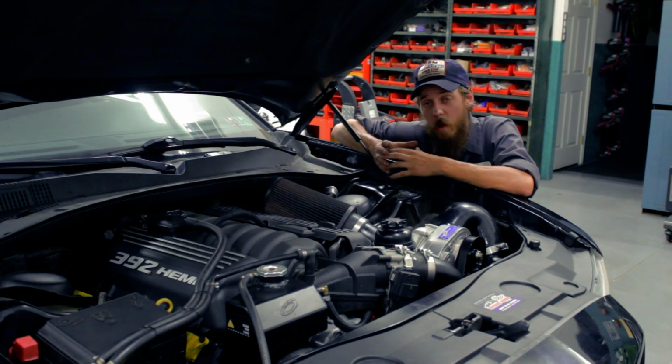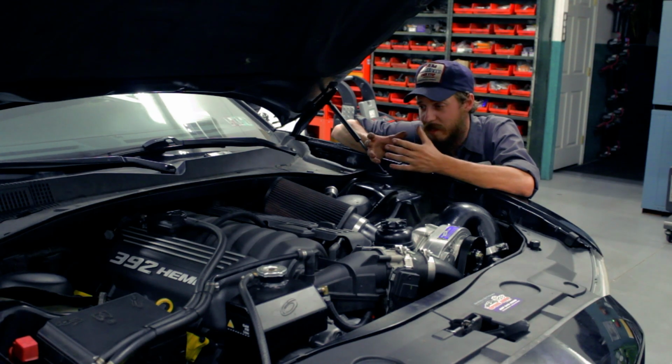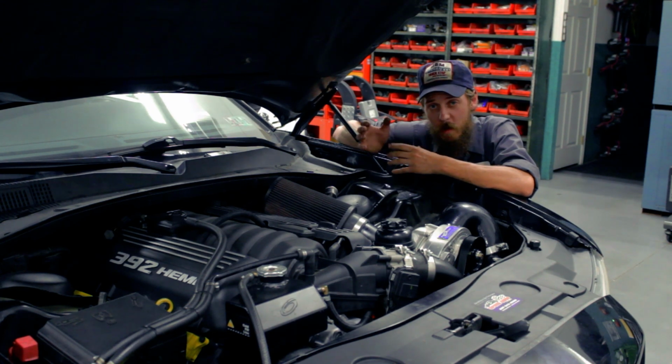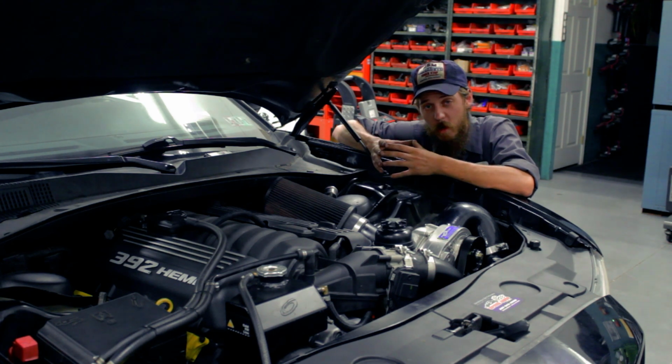I mean, how would the car know it's out of range? It goes with the simplest programming, the easiest. In this case, it looks at the fact that despite the fact that we see multiple park neutral inputs that all agree, I see this voltage lower than it should be, so I'm going to inhibit cranking.